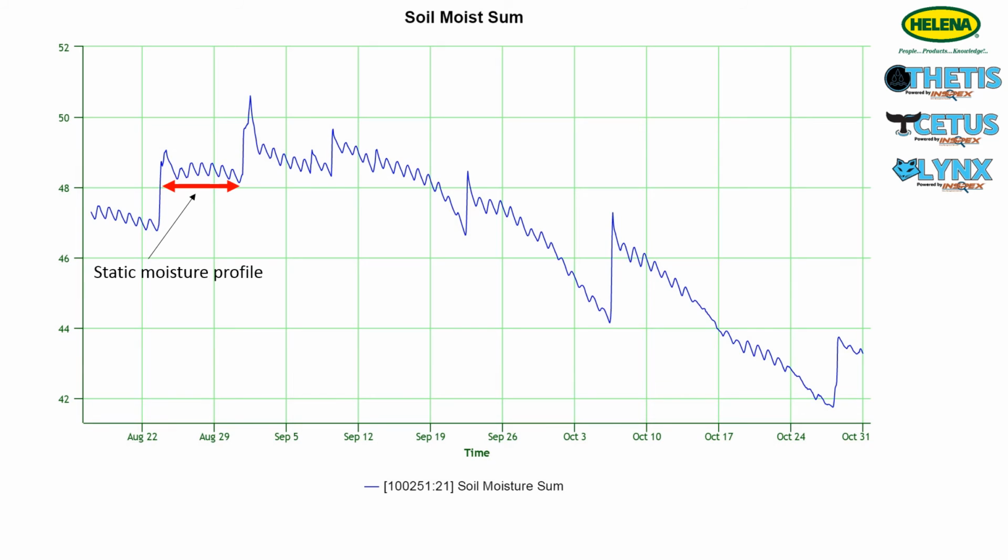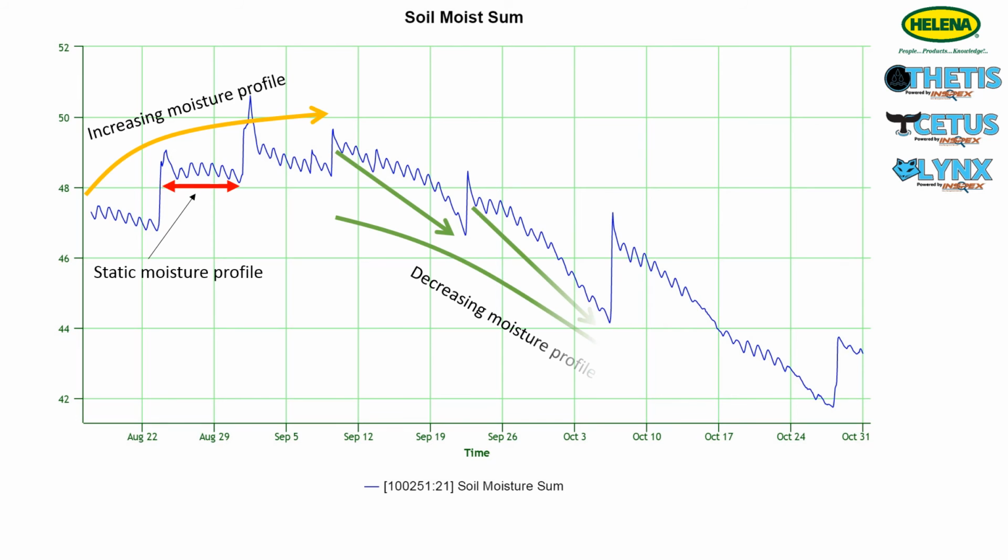When the irrigations are relatively frequent and the soil moisture profile is already near capacity, then relative soil moisture for the profile will change very little. Reducing the frequency of irrigation or shortening the duration of irrigation will allow you to utilize the soil moisture already available. Continuing to irrigate more frequently than needed or running the set length for extended periods of time can lead to increasing relative soil moisture. Lengthening the irrigation frequency allows the crop to draw from existing soil moisture reserves.